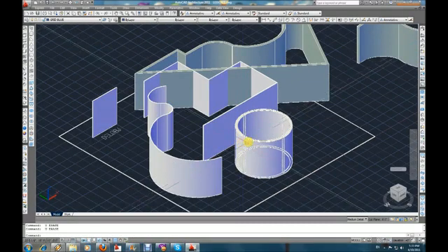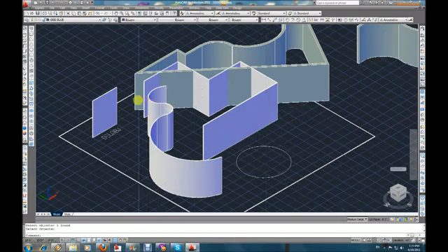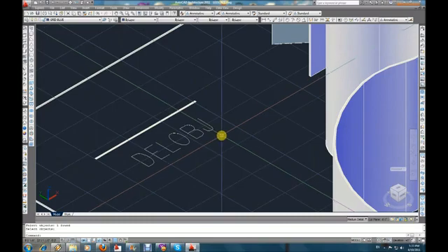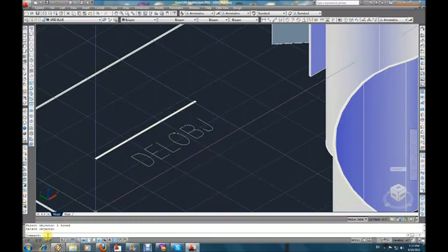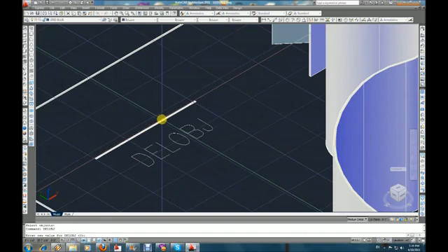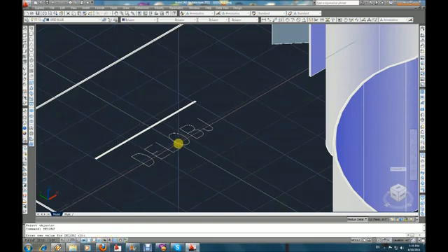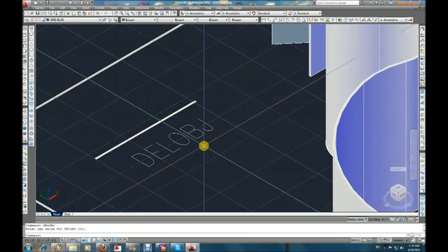There is another item to mention. If you delete these polysolids, you can see that the line and the circle are still there. The command DELOBJ stands for delete object. If you go to the command line and type in DELOBJ, enter, right now it's set at 0, which means it's going to leave whatever you had in there alone. There are 7 options: 0, 1, 2, 3, -1, -2, and -3. Please go to help on your AutoCAD, and there's a good explanation for those on the website.